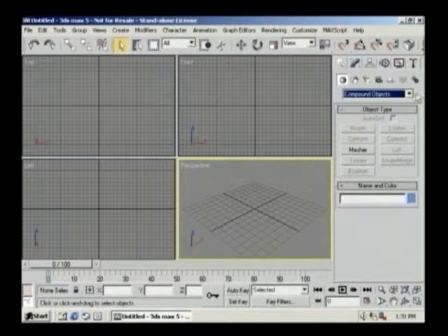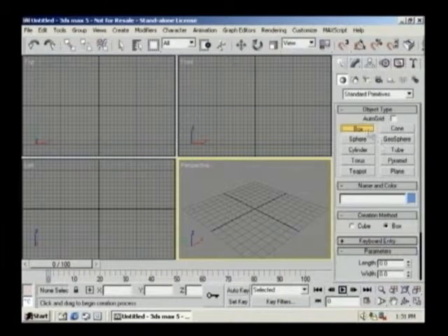Make sure that you are at the Geometry section, and our sub-selection drop-down menu is Standard Primitives. Here you see a variety of different standard shape geometries that we can create. I'm going to activate the Box button, and then the box creation parameters appear on the Create panel. The box is indented. It changes to yellow just to make sure you know it's active. And the most basic way to create geometry is to simply click and drag in the viewport.